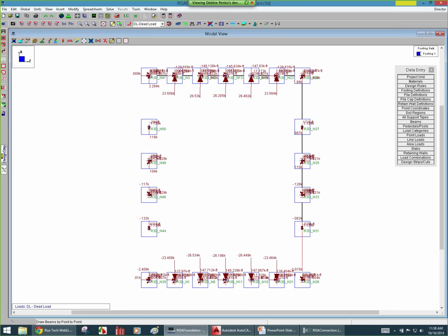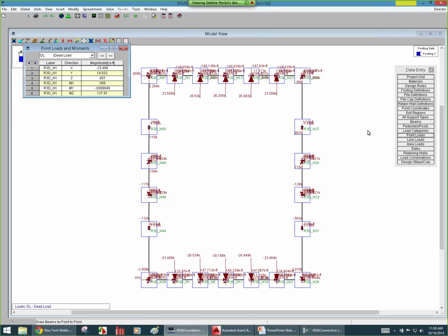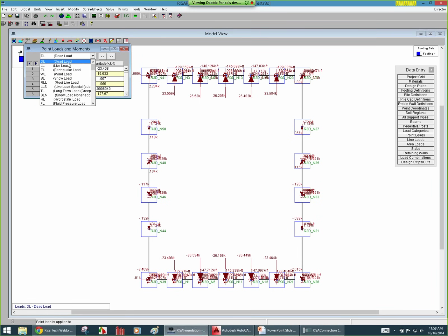And then the program, since you can see the dead loads are displayed right now, but all those end reactions, so for the wind and whatever other types of combinations you created over there in RISA 3D, what gets brought across is the categories. So when you look at those loads here, those point loads, everything is categorized there based on the load categories you use in RISA 3D. So live load, if you use anything, you can see it's all listed here based on those categories.